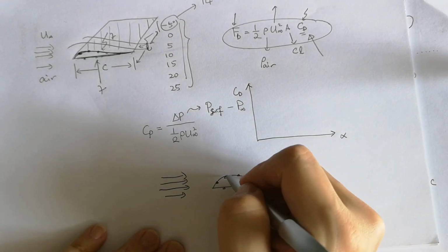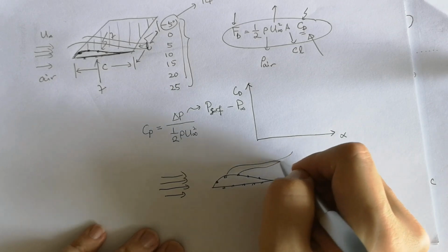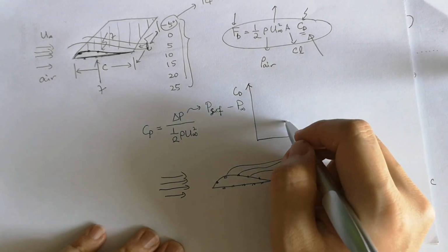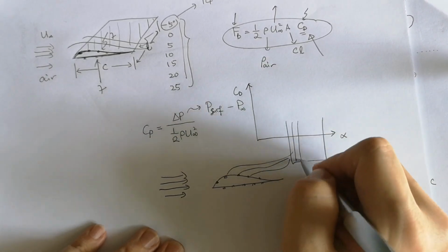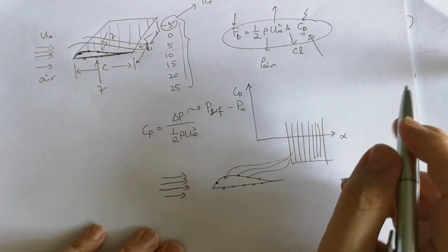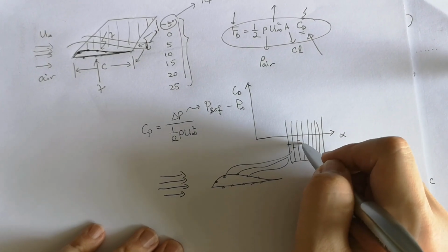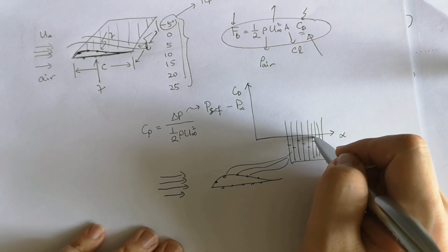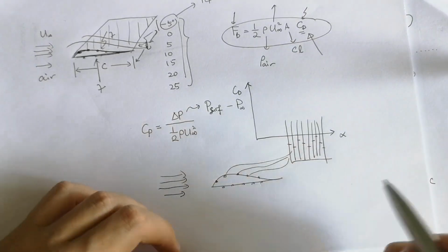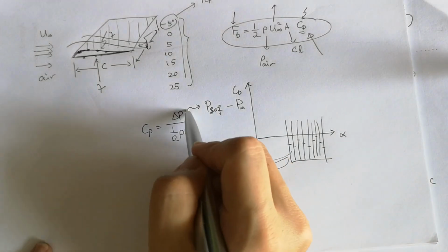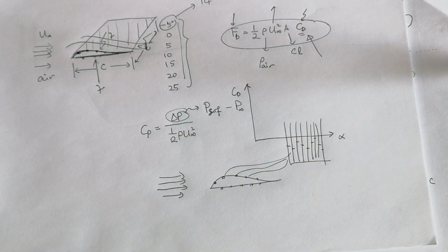That's why these readings will be connected to a manometer board, and you're required to record the water level rise or fall. We will take this reading and convert it into our change of pressure later on.